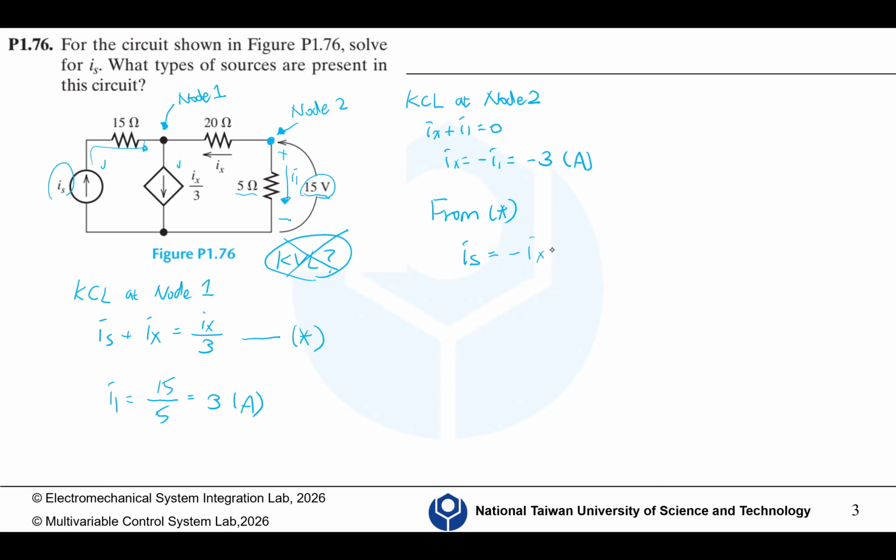And then node 2. If we assume there is current flowing into node 2 in this direction, then we have V1 minus V2 divided by 5 plus 10 ampere plus, I assume that current always flows into the node, V3 minus V2 divided by 10 equals 0.